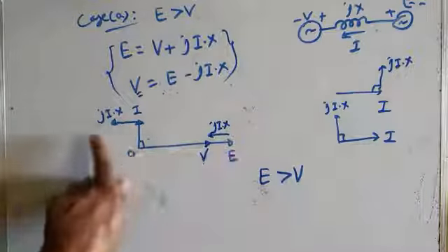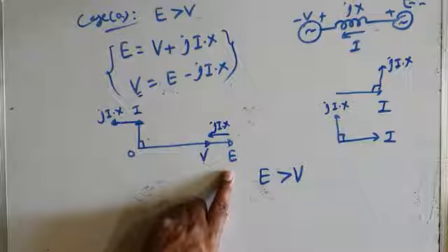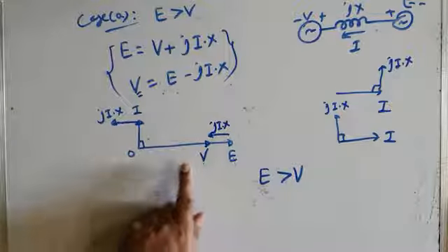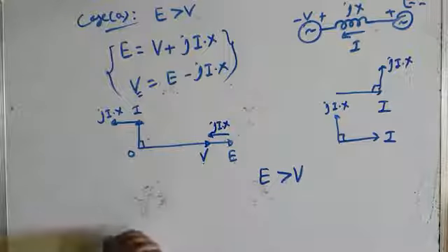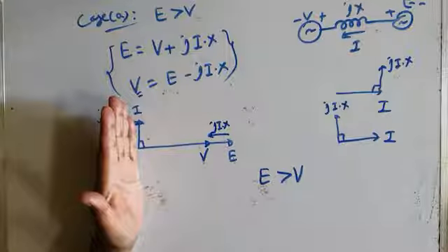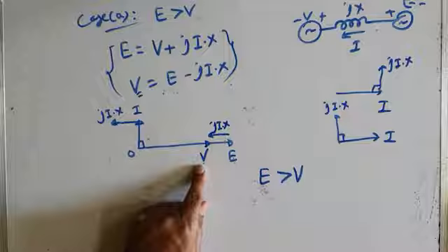So this phasor diagram clearly shows that in the overexcitation state, when the synchronous condenser is overexcited, making E greater than V, this is the phasor diagram. And the phasor diagram clearly shows why it draws leading power factor current, because when the machine is overexcited, it draws leading power factor current that makes E greater than V. Otherwise, E will not be greater than V.